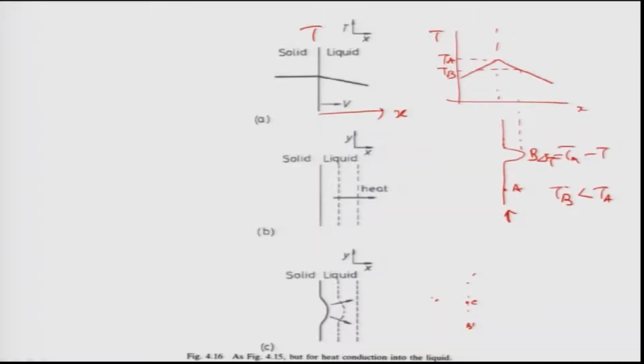Let me try it first. So, what I have done is like this. I have drawn two protrusions, and I have drawn two points B prime and B prime here, and then a point C. This is point A. As point C is getting undercooled more than the two B primes, obviously A is at a high temperature, so the question of A does not arise. Just to show, I have drawn A. Because of this high undercooling at point C, compared to point B prime, the protrusion will form like this and grow. It can go like that.